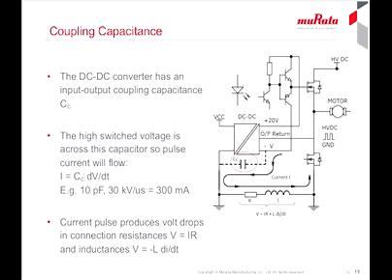It's therefore necessary to choose a DC-DC converter with as low a capacitance as possible. Values down to 3 or 4 picofarads are achieved with some of the converters in the Murata MGJ range. If the level of current is still too high, you could fit a common mode choke in the input of the DC-DC converter to reduce it.